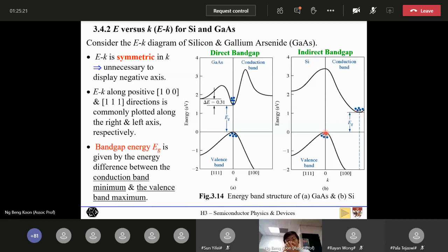Okay, theoretically. But in order to find this exact momentum for it to match, it's a lot harder. It's a lot harder because there's this varying range of momentum. So instead, this process is harder. Instead, what is more preferred for an electron in such a material is that they tend to go back down to the valence band through what we call defect levels in the band gap.